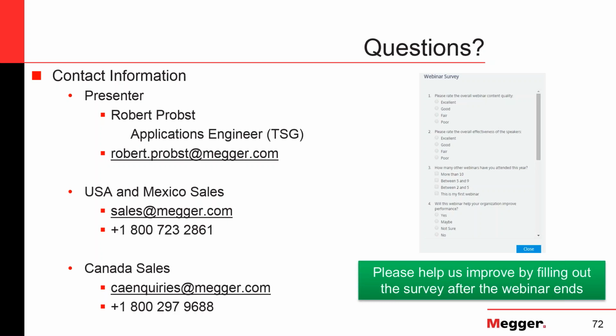A lot of testers are 6 volts, 12 volts, 15 volts in that range. So, I mean, don't do it, but technically you could touch that. You can run 10 kA, you can touch it, and it won't hurt you. It is low voltage, high current. That's the trade-off. And this is why the burdening of the source that I tried to explain with the circuit impedance is such an important thing, because your output voltage is 6 volts. If you consume 5 volts of that just because of leads, inductive loop and voltage drop, there's not much capacity left to drive a high current through that load.